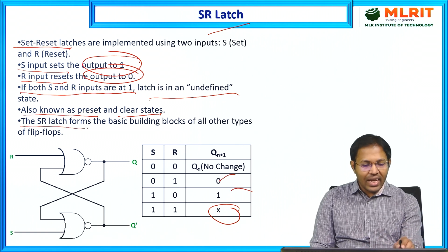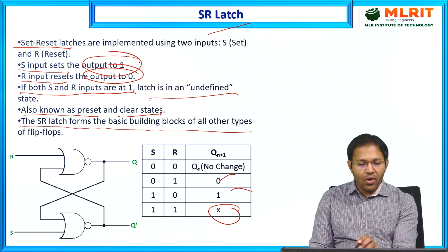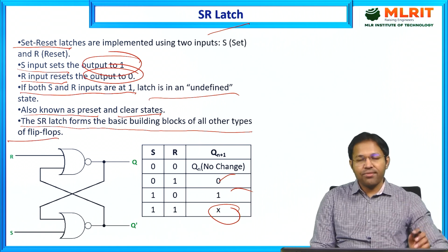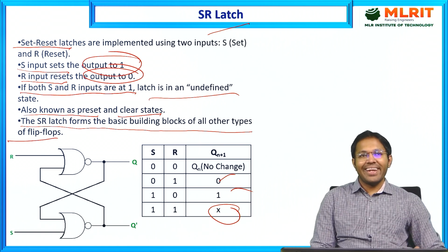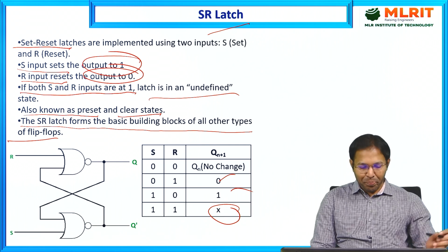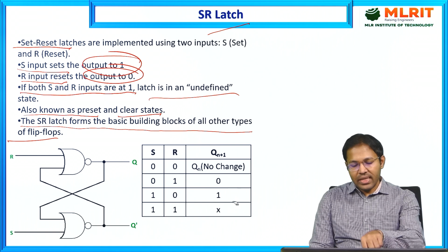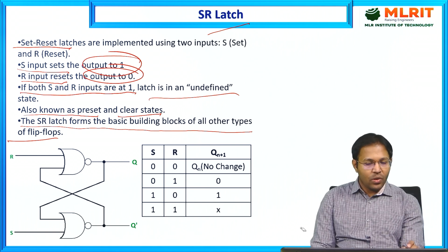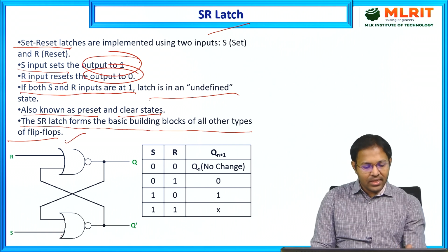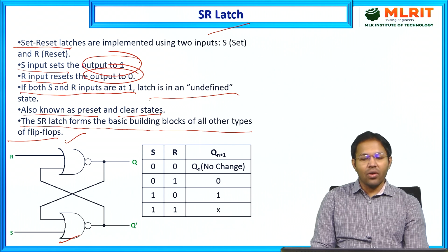The SR latch forms the basic building block of all other types of flip-flops. We can construct different flip-flops by using the SR flip-flop. Okay, so now let us see how this actually works. So, very simple. Here the structure, we have two cross-coupled NOR gates.